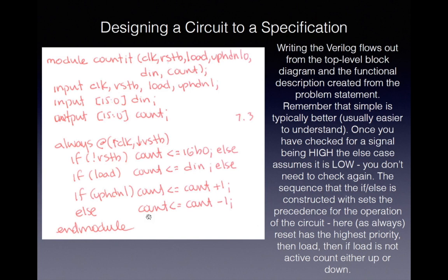When you write the Verilog, by looking at the reset input first, what you're doing is giving precedence to reset. What you look at next, you're giving precedence in the synchronous world to it. Here, it really doesn't make sense to count up or down, then look at load. The only thing that makes sense is if I want to load this, I do that immediately. If I'm not resetting and I'm not loading, therefore I know I'm counting, and then it just is a matter of whether I'm counting up or down.